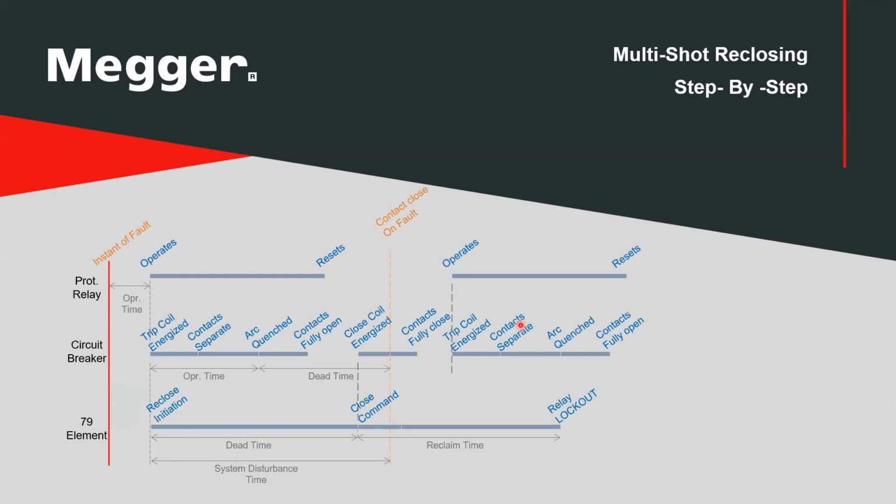So before we move into multi-shot reclosing, let's just take a moment and we'll recap and compare a little bit between fuse saving and fuse blowing. Fuse saving scheme allows momentary outages on the entire feeder, while fuse blowing scheme accepts longer term outages for the smallest number of customers. Understanding that in this case, someone always must respond and reset that fuse. So it is a significant time outage.